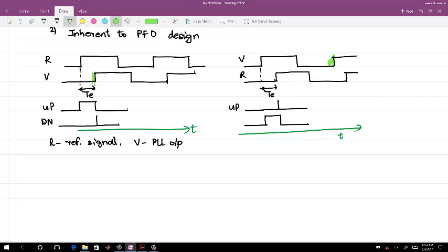You get that thing. For a positive input phase error at a given sampling point, because this is a sampled system, you are actually changing the feedback signal, so you are not exactly controlling the same phase error which is given at that instant. It's changing continuously.